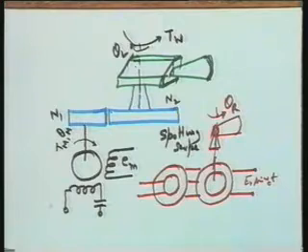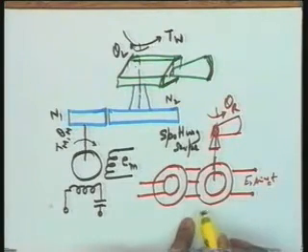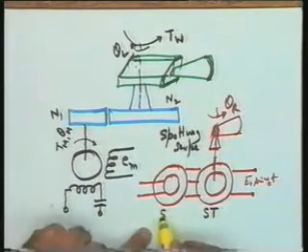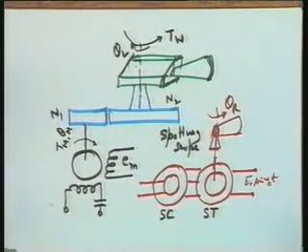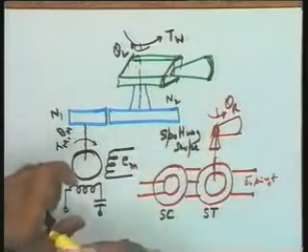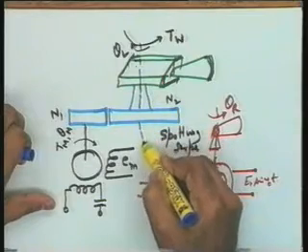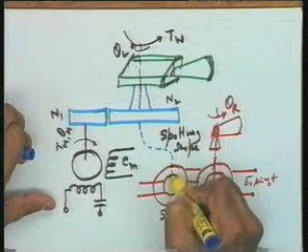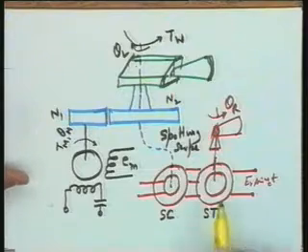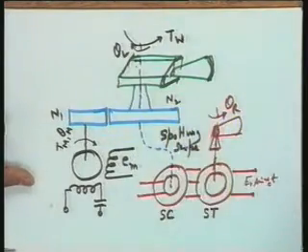Tell me please, how do I connect this synchro pair? Just see, this is your reference signal of the synchro transmitter. This is my synchro transmitter device, and this is the synchro control transformer. Though it has not nicely come under this particular diagram, I think it will become clear if I connect this. This particular gear is mechanically connected to this rotor, so that the input to this synchro pair is theta_r minus theta_L.